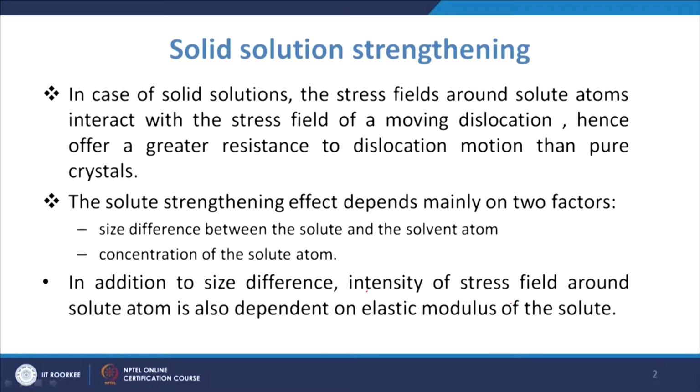As we discussed, in the case of solid solutions, the stress field around the solute atoms interacts with the stress field of a moving dislocation. So you have these two stress fields interacting with each other, and in that process there is greater resistance offered to dislocation movement in solid solutions than in pure metals.